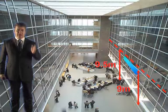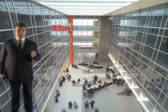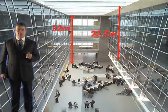So we shall adopt a height of 9 metres plus 0.5 metres, which gives you 9.5 metres from the equilibrium height at the base of the smoke layer. Therefore, the smoke layer will be 32 minus 9.5, 22.5 metres. That's the depth of the smoke.